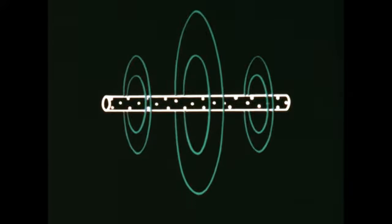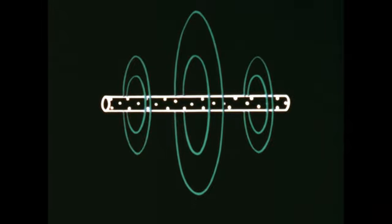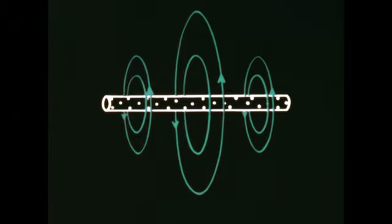Let us relate the direction of this field to the electron flow. As the electron flow reverses, the magnetic field is at a maximum, and the lines of force are in this direction. When the flow stops, the lines of force collapse. As the flow reverses, the field again reaches a maximum. The lines of force are now in the opposite direction. The magnetic field thus reverses its direction at each half cycle of the signal frequency. This is known as the H field.